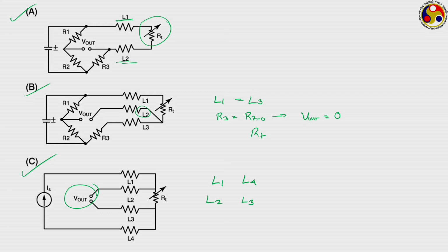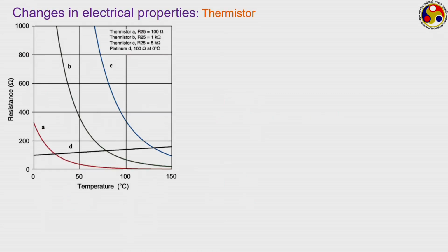But there is another kind of resistance based temperature device which is called thermistor. Thermistors are semiconductor based devices and their operating principle is just opposite to the RTDs. Thermistors generally are made of materials having a negative temperature coefficient of resistance. The RTD materials generally have a positive temperature coefficient, so that with increasing temperature their resistance increases. But thermistors are made of semiconductor devices whose resistance decreases.